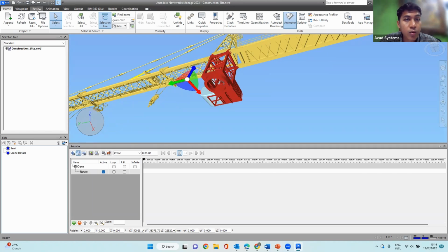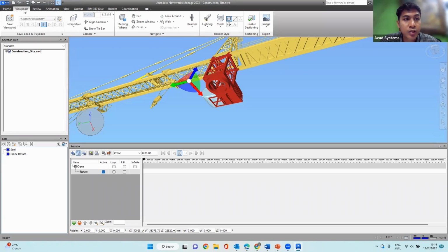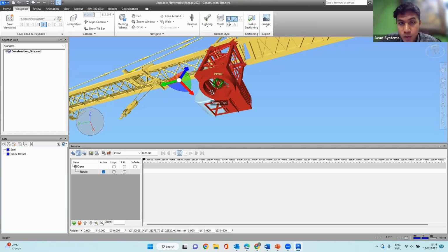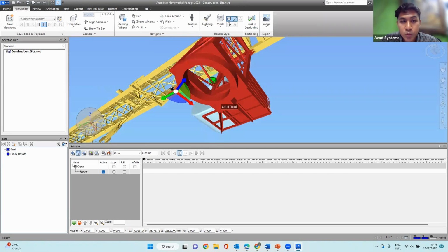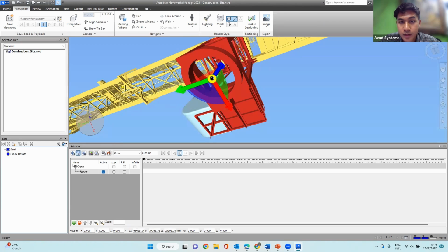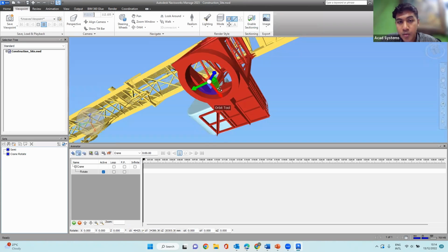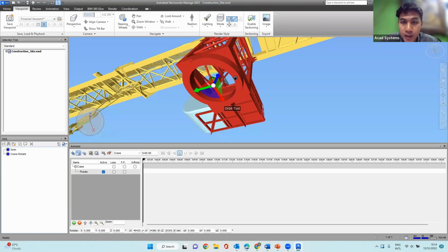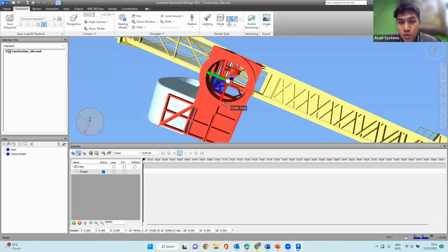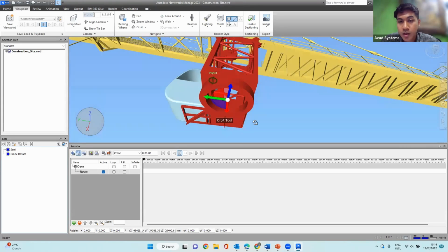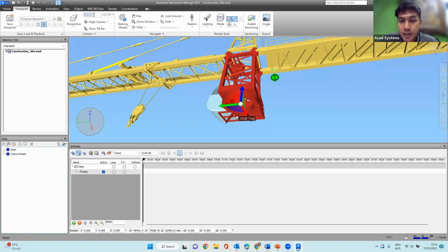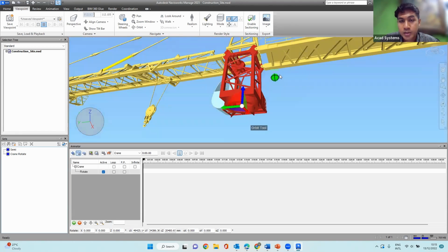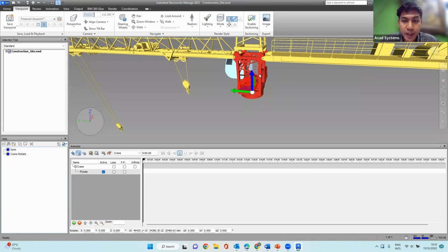Before I drag, I want to go to the viewpoint tab, and turn on the line display because I know in this model there is a line that shows the center. So when I bring this gizmo, I can snap to that center. Maybe when you model this and you know that you want to apply an animator in whatever software you use to model, it's good to include an indication for the center of rotation, like what I did here. So I can turn on this line and snap to that line for our gizmo. Now we've brought our center of rotation here.